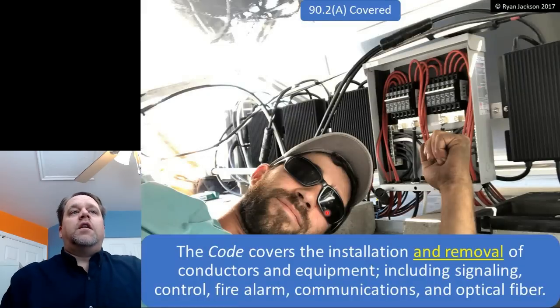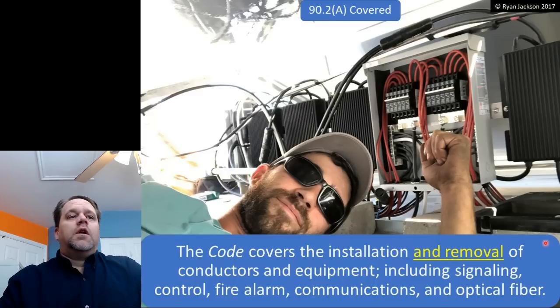All right, 90.2, the scope. This is a really important section. 90.2(A), installations that are covered by the code. What does the code cover and what does it not cover? Well, 90.2(A) says the code covers the installation and, new to 2017, the removal of conductors and equipment, including signaling,